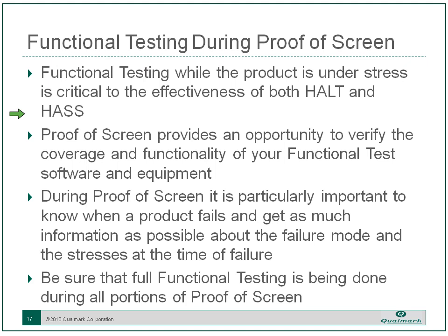And remember that a key part of functional testing is power cycling. And power cycling should be done both during the hot and the cold portions of the screen. At cold, power cycling is more fatiguing because your product is nice and cold before you turn it on to get it hot. You leave it off long enough to cool down, which is a minute or two. In hot, you're more likely to see errors due to startup timing issues, because when all that electronics gets hot, it's more sensitive to timing issues. So you're really looking for two different classes of failures when you power cycle cold versus power cycling hot.